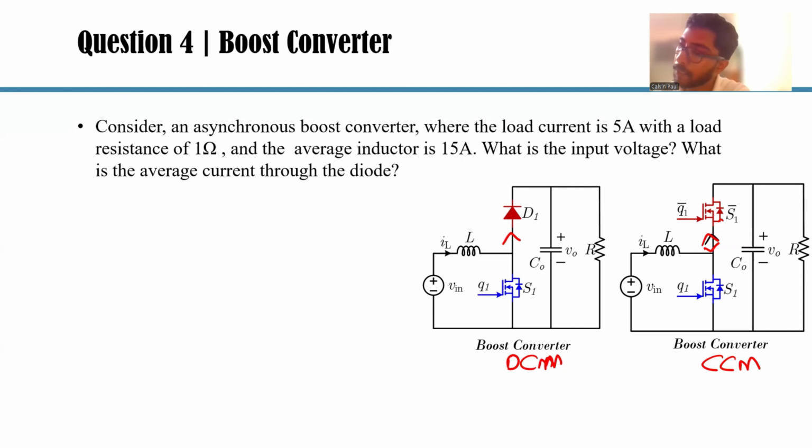Secondly, there are certain scenarios where we want to flush out the charge stored at the output voltage quickly. In that case, we want the current to go in bidirectional operation, so we operate it in CCM mode. Okay, DCM also is widely used. You can make this converter, which has this switch, also operate in DCM.